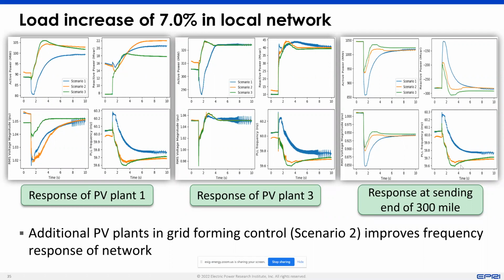Actually, the point on that 70-30% rules of thumb, I'm deviating from this, but it's good to deviate. We found that depends a lot on how you represent load. What kind of load characteristics do you use? Do you have static load versus motor load? Do you have three-phase induction motor load versus single-phase induction motor load? Do you have distribution connected resources? Those rules of thumb vary so much depending upon the type of load, which is now making it more challenging to define a rule of thumb.